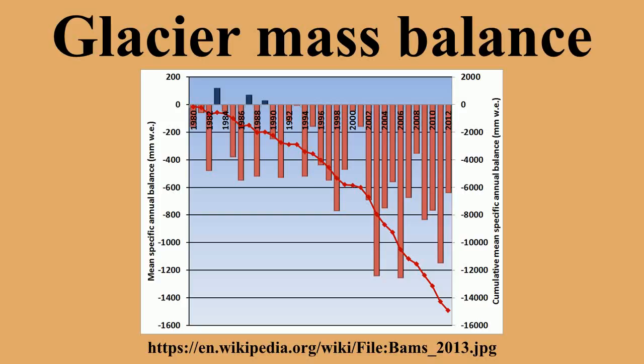Iceland Glacier Mass Balance. Glacier mass balance is measured once or twice annually on numerous stakes on the several ice caps in Iceland by the National Energy Authority. Regular pit and stake mass balance measurements have been carried out on the northern side of Hofsjökull since 1988 and likewise on the Þrándarjökull since 1991. Profiles of mass balance have been established on the eastern and southwestern side of Hofsjökull since 1989.